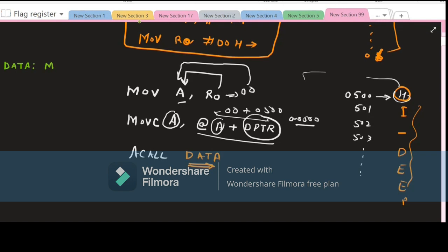In this also, we have to write the same simple lines. We have to do MOV P2, A. Whatever data is coming this time, we want to send to port number 2. Now we want to send this data to the LCD. Before sending it, we have to select the bit, that is the RS pin. So we have to set the bit P1.0, and then again clear the others.